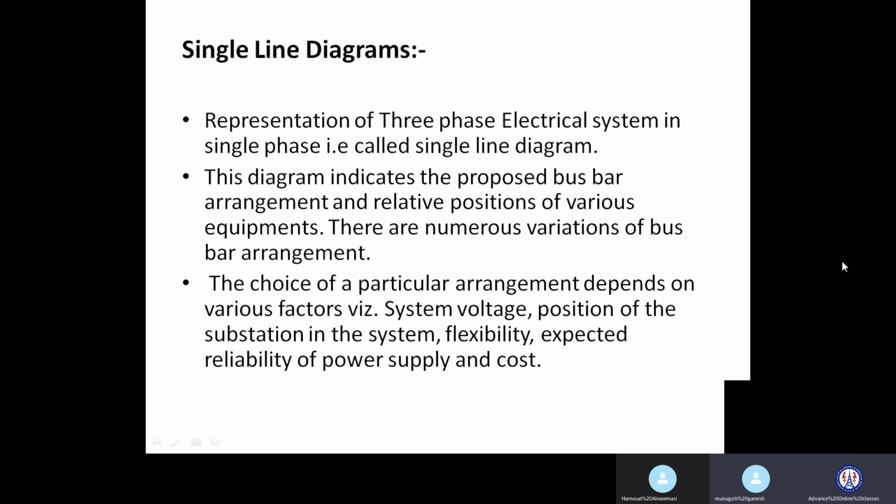50%. So basically your 33 kV feeder, a standard fault current rating is 25 kiloampere. And your 11 kV system, a standard fault current rating is 25 kiloampere. So you are considering the fault current rating of your incoming feeder, that is 33 kV, as 25 kiloampere. And your outgoing feeder is working at voltage level 11 kV and its fault current rating is also 25 kiloampere.